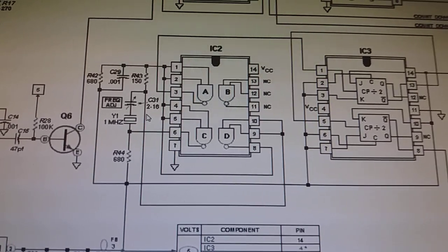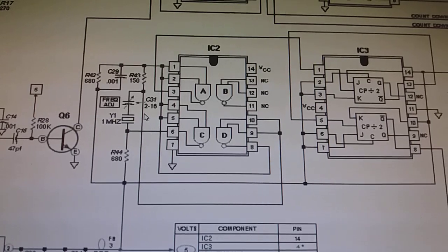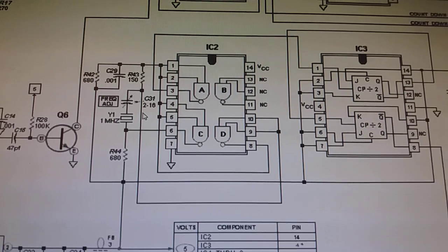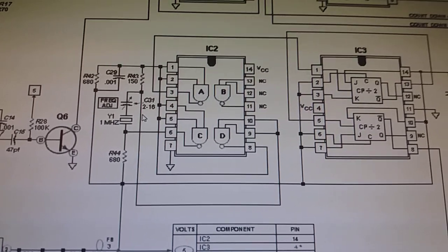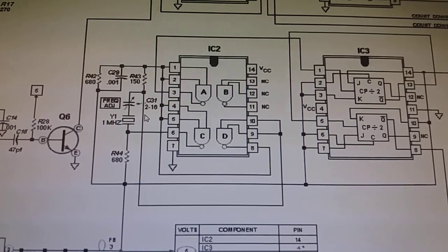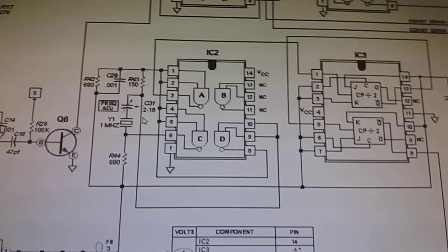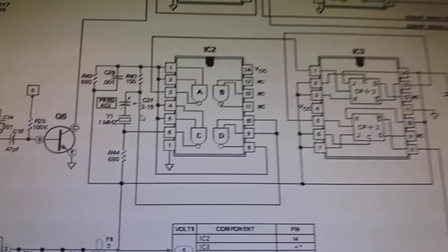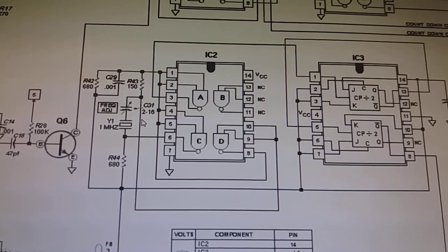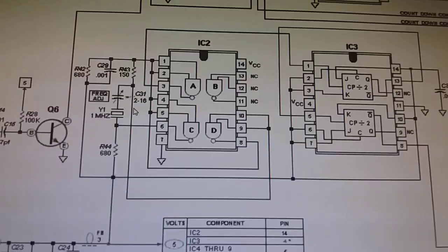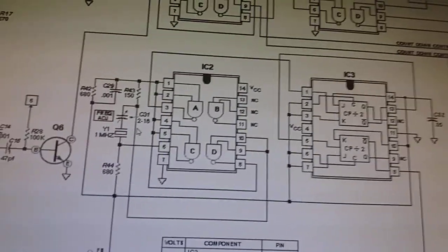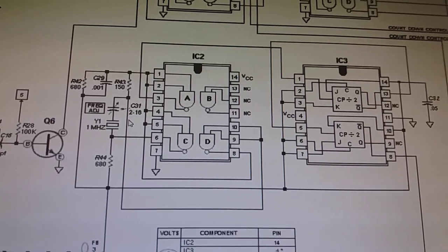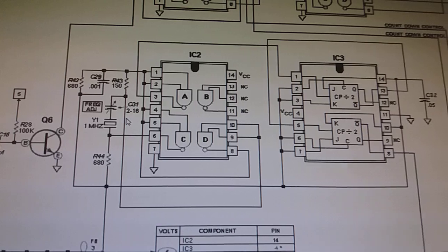Okay, and we might end up completely removing this variable capacitor. I don't know, maybe the PCB traces are close enough on this variable capacitor, and maybe that's enough. But really it would be nice if we had a way to vary very small capacitances here. So I think I'm gonna try the series capacitor method, and see how it goes.